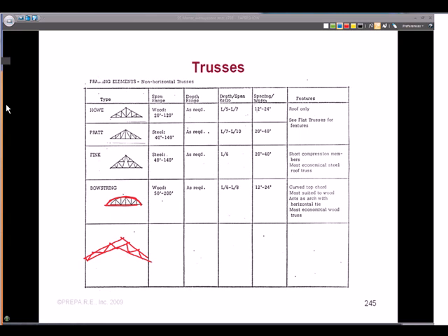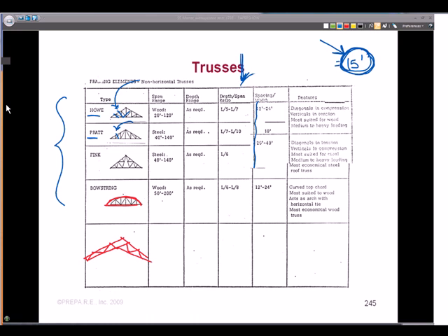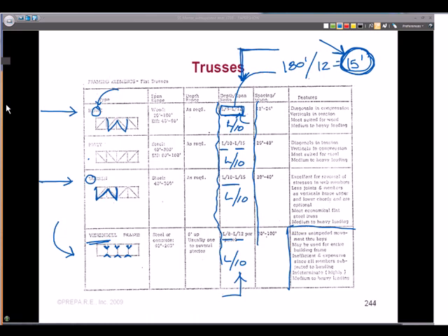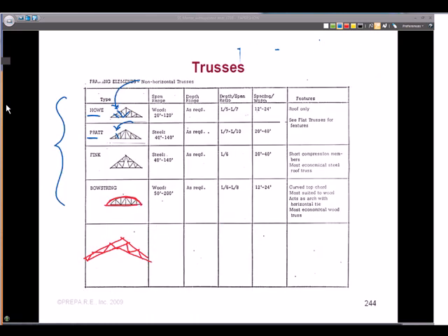Okay, so be familiar with just the various truss names. Again, now we see the Howe in the Pratt truss. But now, with the pitched top chord, or the non-parallel truss chord, do you see that the diagonals have changed directions versus the parallel chords? If you compare the Pratt and the Howe, the diagonals have now reversed.